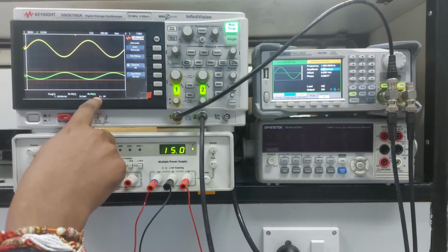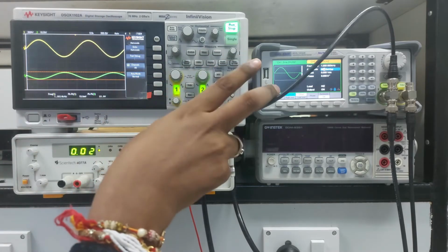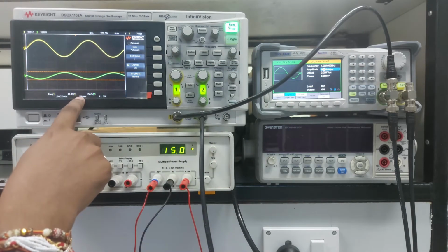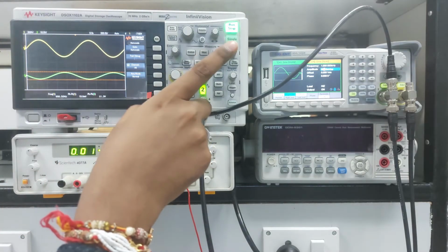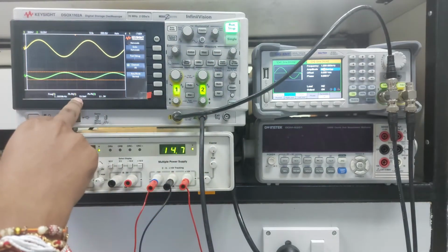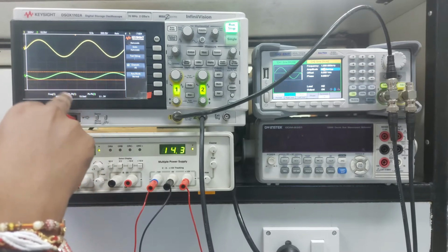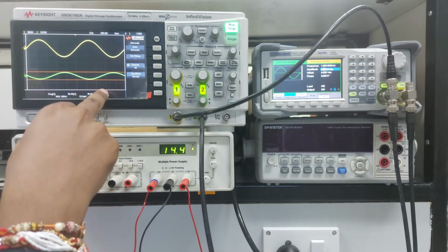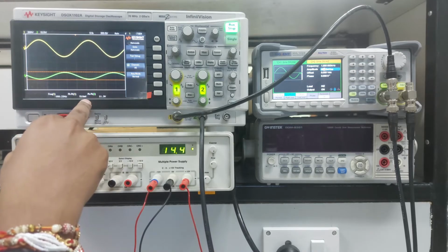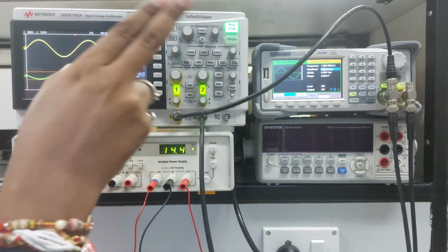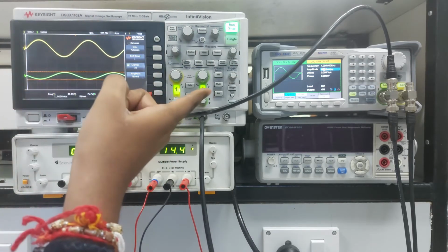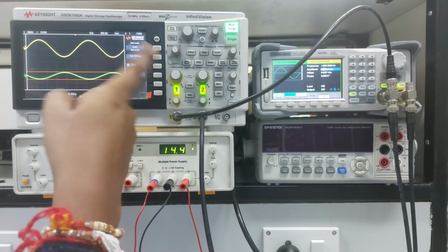which is fluctuating 10.9 to 11.1. So this is 5.1, 510 millivolt in each input. So that means the sum should be 1020 millivolt, that is about 1.2 volt we are giving, and the output should be 10 times, right?